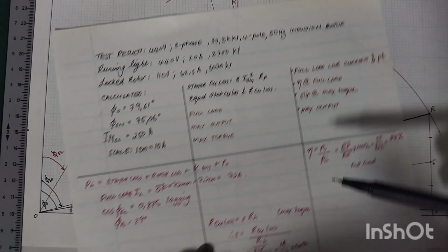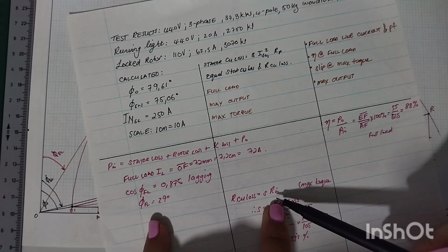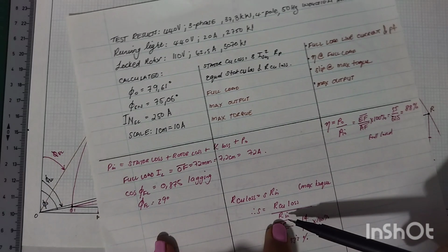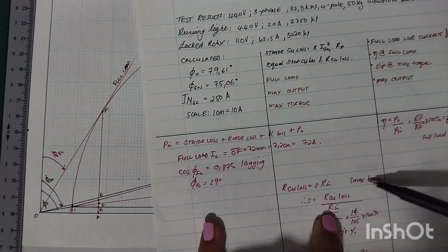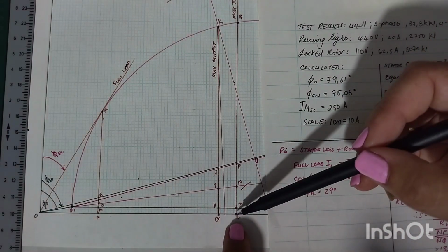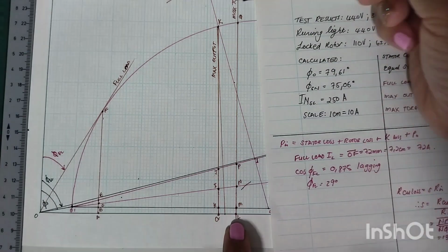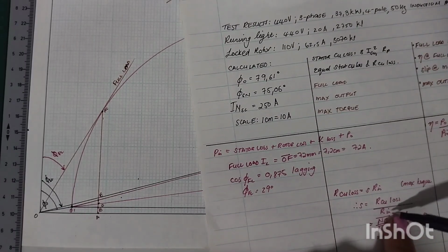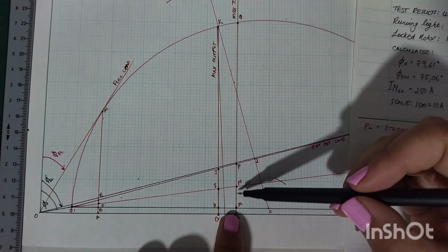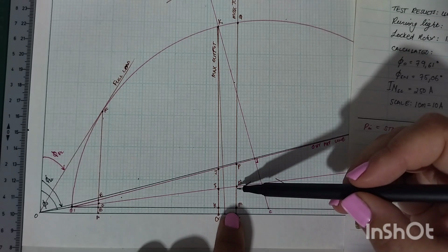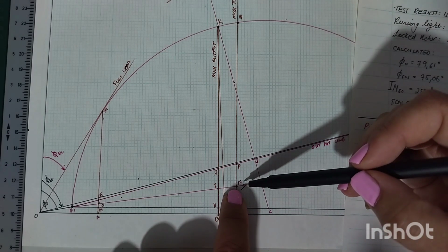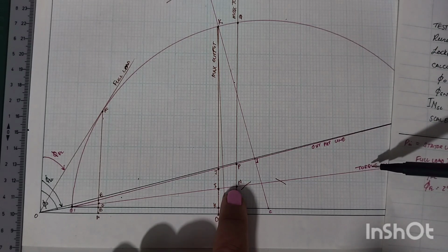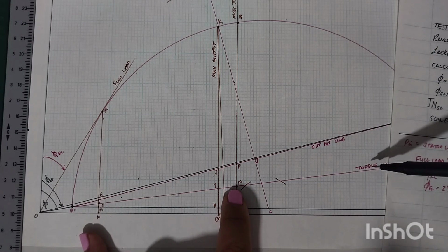The next thing is we want to calculate the slip at max torque. So just a reminder, this is the one I remember, that your rotor copper losses is equal to your slip times your rotor in. So therefore your slip is equal to your rotor copper losses divided by your rotor in. So again, it's for maximum torque, so you go to your maximum torque line to get this information. The distance from your torque line to the perimeter of your circle is your rotor input. Remember the flow of energy. Your stator out is your rotor in. And from your torque line to the perimeter of your circle, that is your rotor in. Your rotor copper losses is the distance between your torque line and your output line.